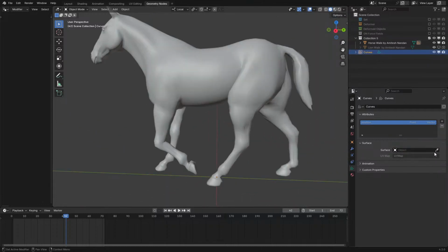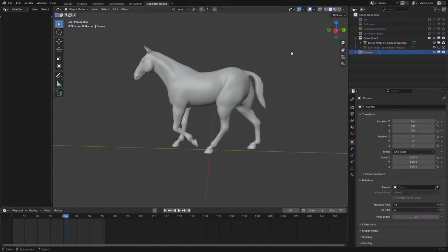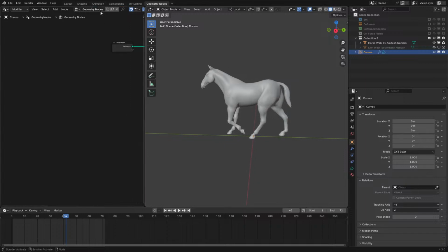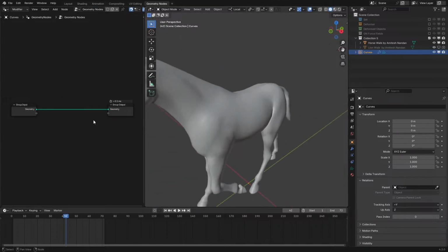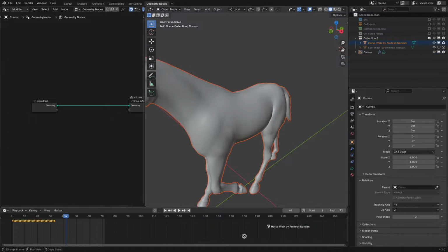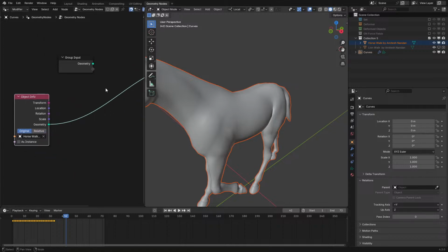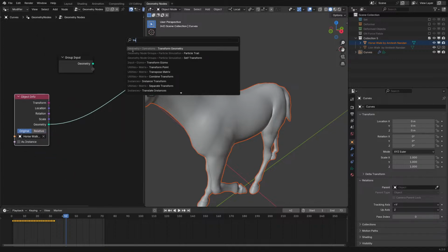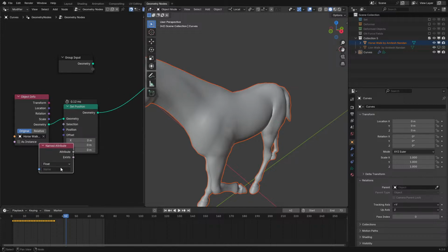But in my case, I'm going to remove all attachment to the original mesh because I want to handle everything with geonodes, because in my cases it's been just a wee bit more stable if I do it this way, if I plan everything from scratch. So in this case, we're going to bring our horse into here, set this to be original, because we want the horse in the rest position. Let's go and set the position and use the rest position, which is right here.